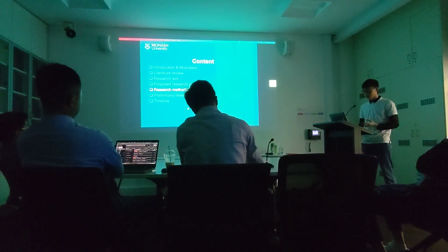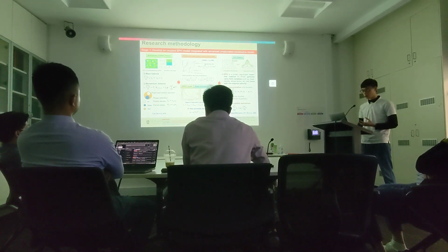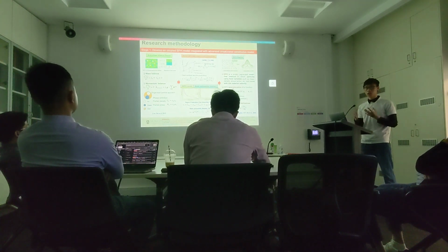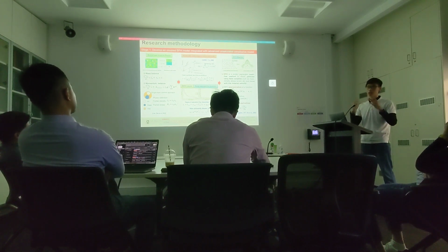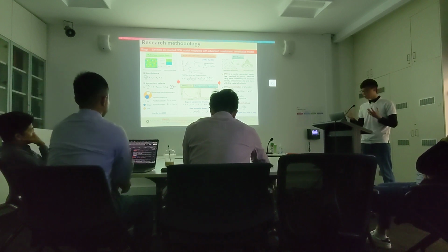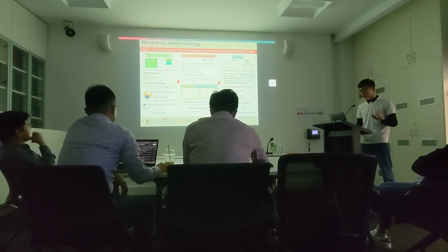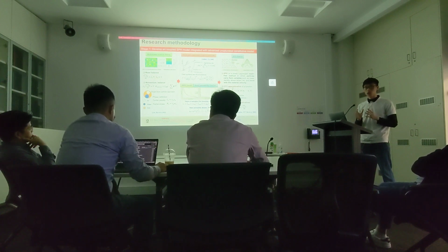Research methodology. So first, we develop a coupled HPX framework with an advanced unsaturated constitutive model. We start from multi-phase mixture theory, where we have the mass conservation equation and momentum conservation equation. By solving the equations, we get the increment of pore pressures, and by summation of the momentum equation of each phase, we get the increment of velocity. To solve the equations, first we need the stress-strain relationship by using this constitutive model. We also need the degree of saturation and water permeability function. Finally, to solve the equation, we need the spatial derivative. This is the way that we need to use HPX.